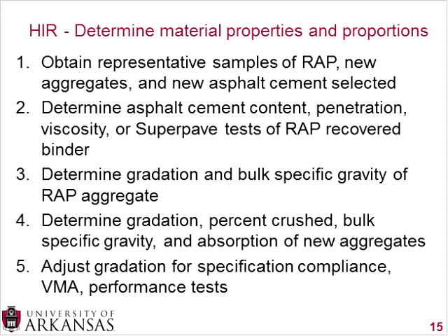So whether you crush the aggregate, which would be a little more representative of the milling, or you heat it and bust it apart with a spoon, the important thing is to try and simulate what you're doing in the field so that the existing asphalt concrete behaves in a similar manner.